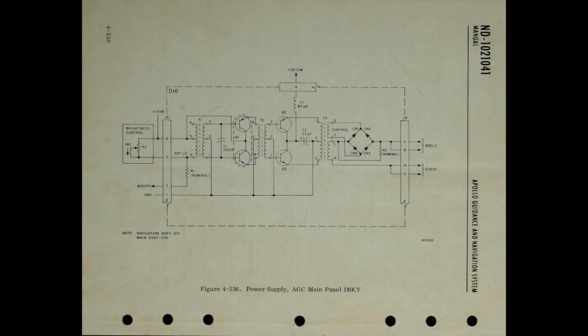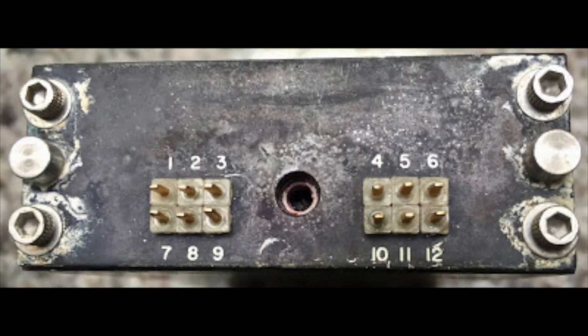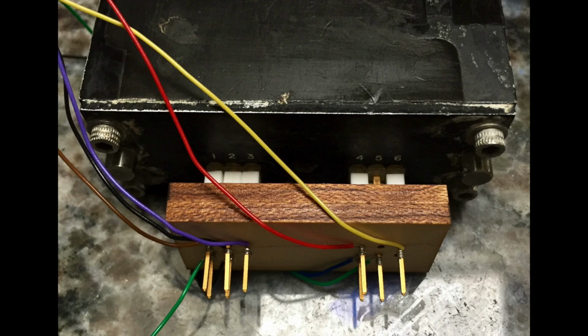Then you need a source of 250 volts AC at 800 Hz. We had the schematic of the power supply, which was a bit tricky to reproduce due to the last saturable transformer used for regulation. But we did not even have to bother with that, because Marcel had an original power supply module from the Block 1 DSKY. Incredible! And it was mostly compatible with the Block 2 screen, so we were good to power up the Block 2 display with an original Block 1 high voltage supply.